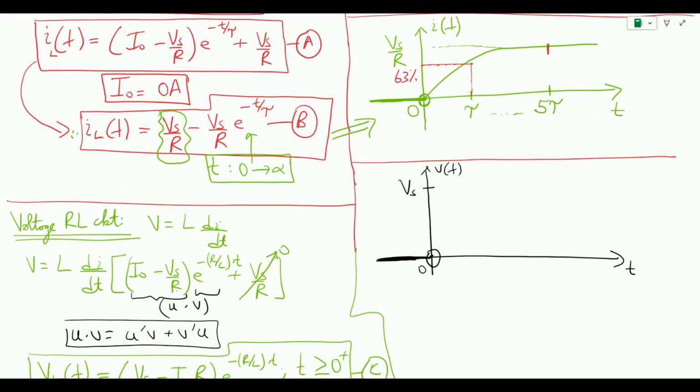So previously we talked about inductors, that inductors don't allow the abrupt change of current, but we can see from here that as soon as the inductor starts receiving energy from the voltage source, the first thing that it encounters is a maximum value of the voltage source, which we can also justify. Consider the same circuit where we have a voltage source followed by a resistor and then an inductor, and this was the switch that we had.